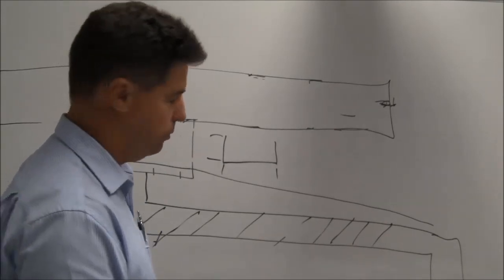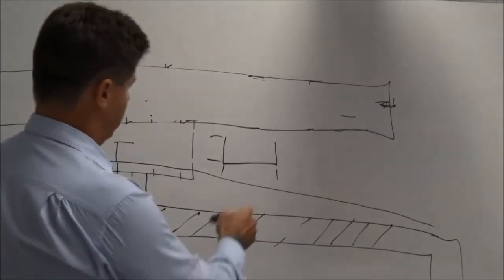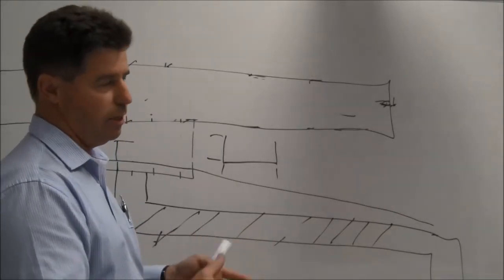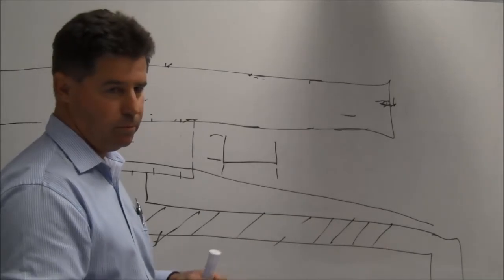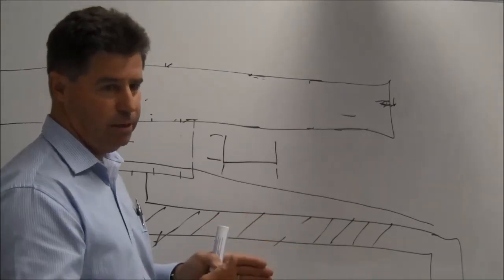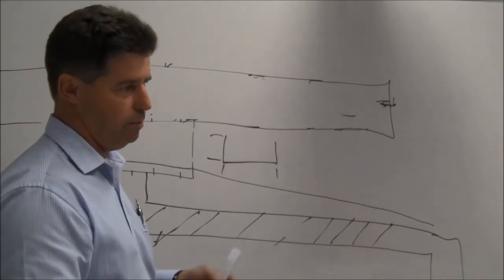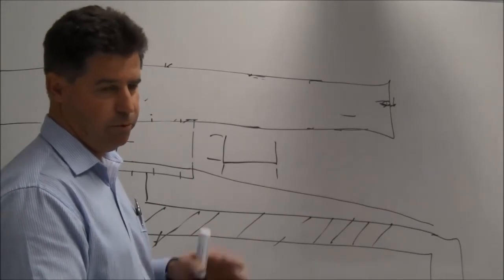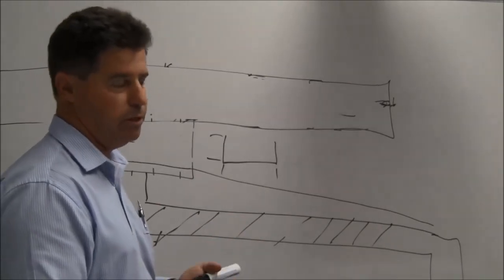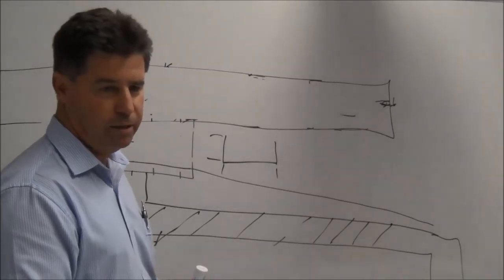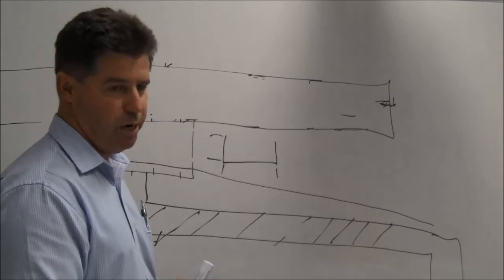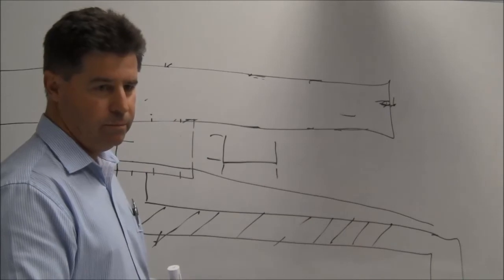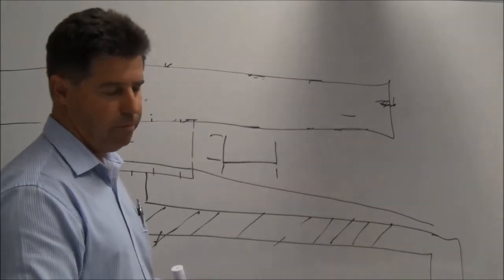That's right. And obviously, the eave gutter sizing gets down by reducing the amount of water coming into it. Therefore, we either make the gutter smaller or have more outlets. So we reduce the amount of water coming into the gutter by having more outlets in it, or we have a specially made gutter with fewer outlets. But whichever way you want to do it, you might be restricted in the amount of downpipes and outlets you can have in a gutter, not through your own doing, but there could be architectural reasons why they don't want downpipes in certain positions. That's what you told us. You said 4 outlets, maximum 4.